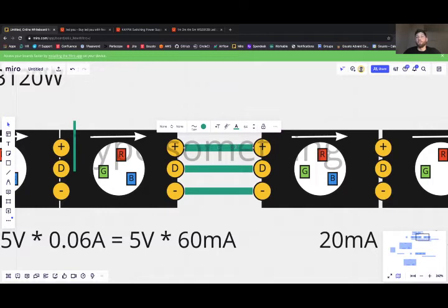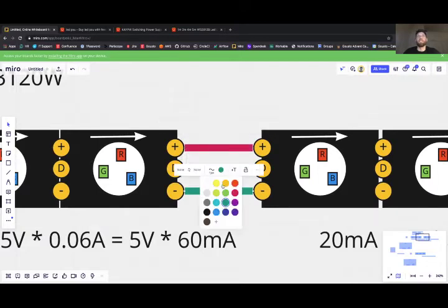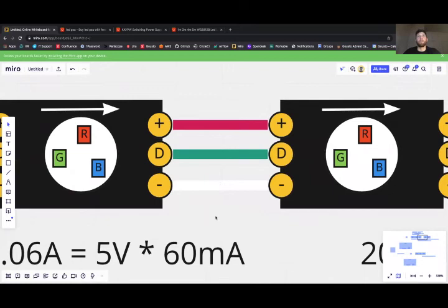soldering will be required. So you'll need a soldering iron, you'll need solder. Lead-free solder is preferable for health reasons. You'll need flux, which helps the solder melt. And you'll need some way of safely cleaning your soldering iron tip. So look up a guide and learn to solder. Soldering is super useful. You can also use it for fixing any home appliance. And it makes you feel kind of like a boss when you solder something and it works again.